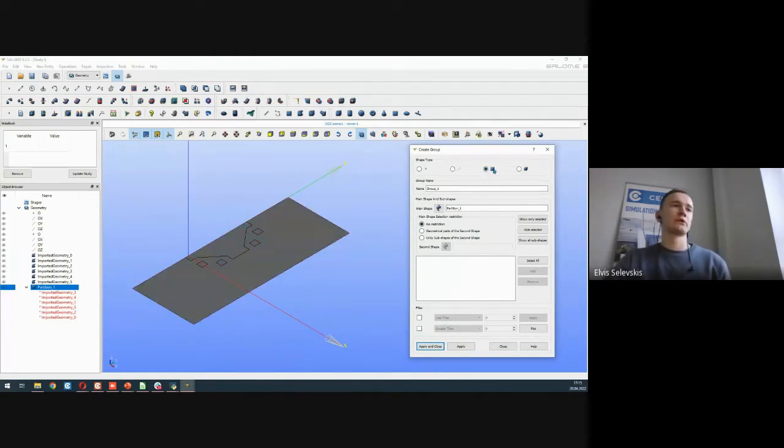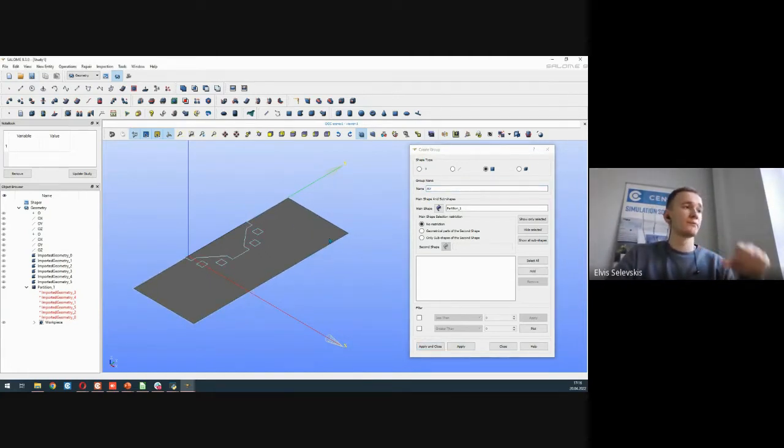All right, then let's start with the faces. Click on the faces button, write the name for the first group which we would assign. Let's say the workpiece. Write it in, and here very nicely just click on the workpiece, press the button add, and press apply. And on the left, you can see that the workpiece group has already been made. In a similar way, we can go with the air group. So write in air and click here on the air face. Press add and apply.